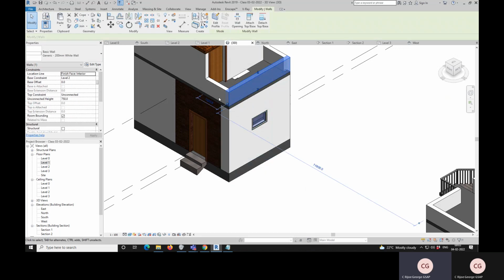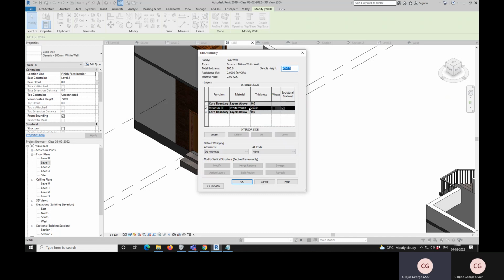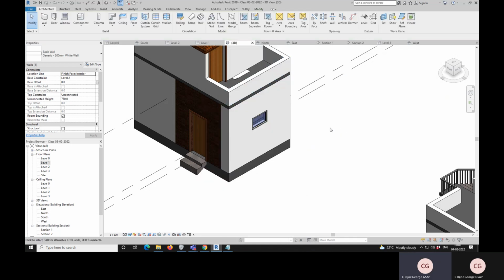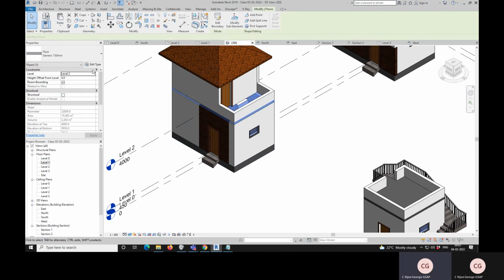Walls, components like wall, you go to edit type, you don't directly see materials and finishes here. See, it is gray. You go to edit type and it will be in material and structure. Three dots, you will get all that. So that is only the two different types. The wall, roof, slab, floor, etc. will have one way of representing it.